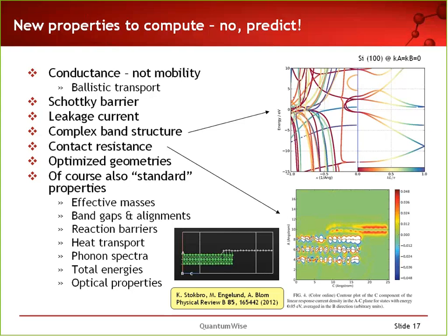These are the bands which are decaying, but if you have a thin enough slice, then they actually have a chance to carry a small amount of current to the other side. So if you have a thin slice of silicon between, say, two metal electrodes, some of these complex bands will give you a tunneling current across, even in the band gap, as you see the red semicircles connect the conduction and valence band. So there are states in the band gap. They're just evanescent. But if the slice is thin enough, they may actually propagate.